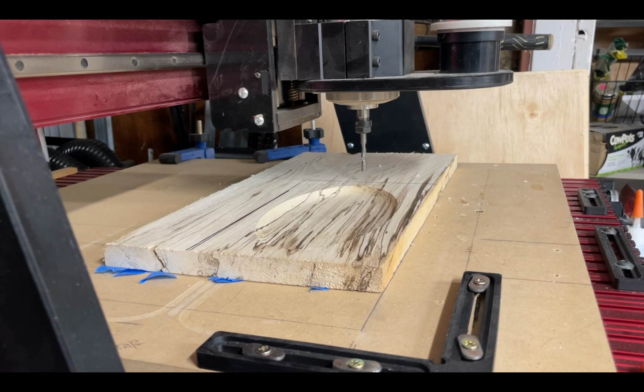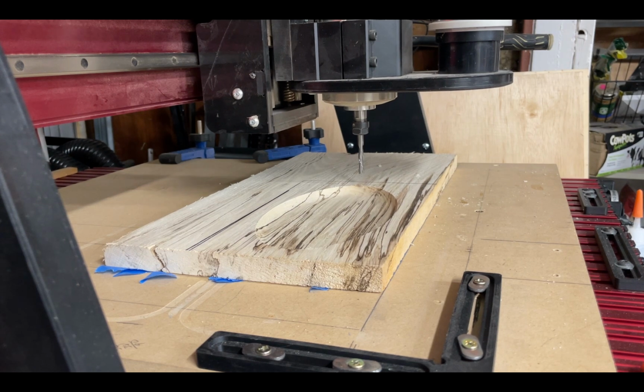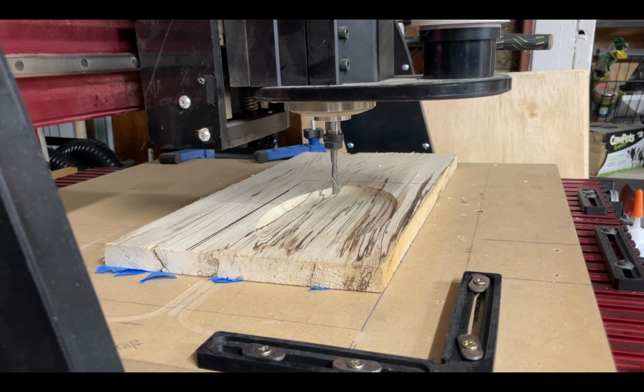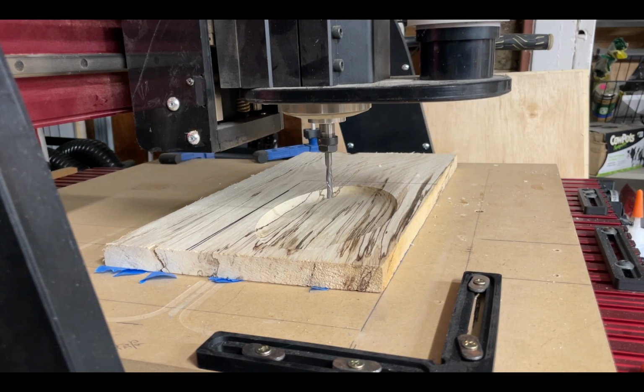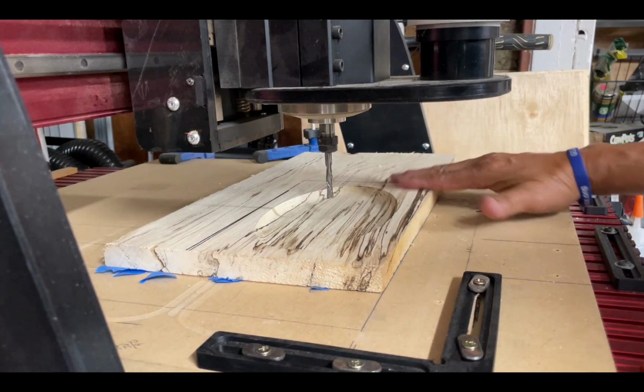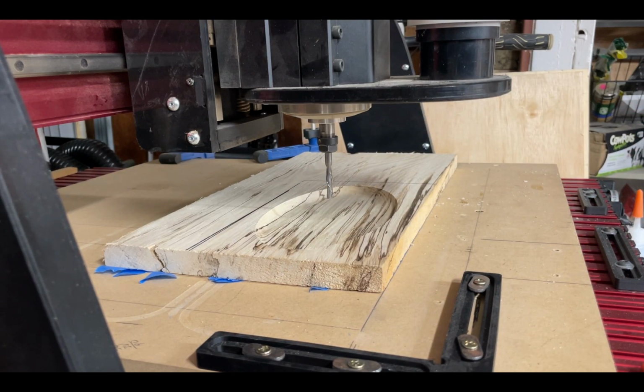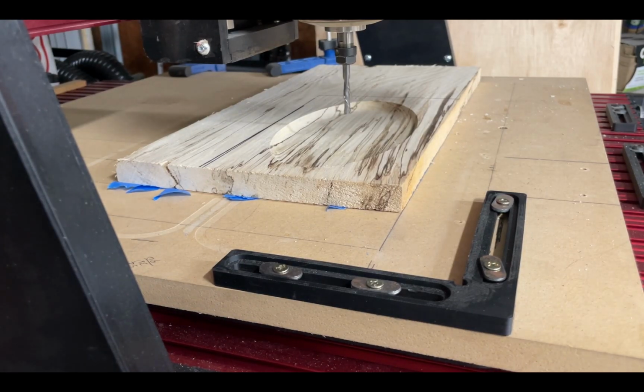All we need to do at this point is get our machine back to XY 0. So we'll go back to our laptop and we'll say move to 0 and move XY. And so now the machine will move back to the original XY position, and it's back in the center. Again, we had to use the Z probe to get us a depth of our original material size.